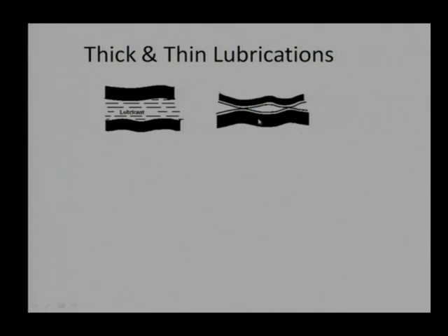So, this kind of mechanism will get disturbed if there is a change in the condition. If we are increasing the load, naturally this lubricant layer needs to be changed, or the material which is required needs to be changed. If we are increasing temperature, there is a possibility that the fluidity of this lubricant layer will increase and it will wipe out or squeeze out easily.